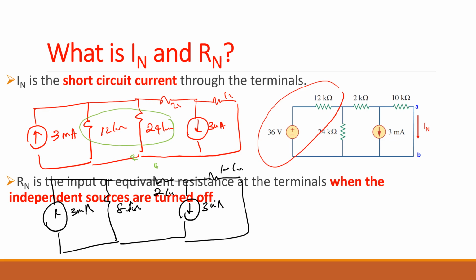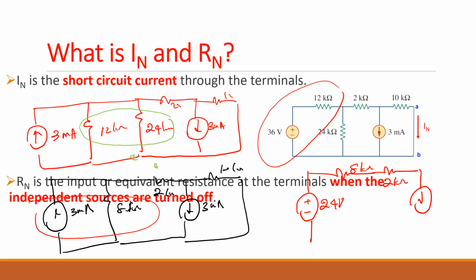Am I right? Now can we convert this to a voltage source? How do we do that? What should be the voltage? 8 times 3, 24 volts, and your resistor will become series, and it is 8, yes. And you have 8 and 2 and 3 like this.